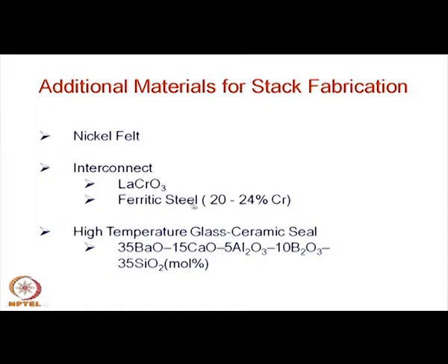I will give you more details of this in another slide. But so far as the high temperature seal is concerned, as has been mentioned, they are basically high temperature glass or glass ceramics. Most of them after cooling actually get crystallized to some extent and form glass ceramic seals.